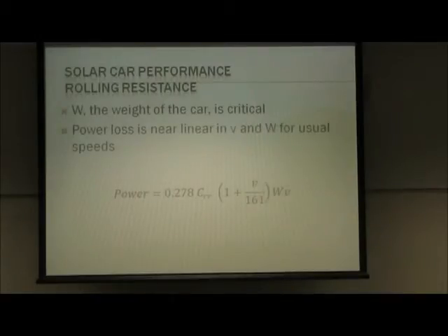And up until 40 miles an hour, that's where aerodynamics and rolling resistance were approximately equal, at least for the last car. So half of your power at 40 miles an hour, plus or minus, is weight of the car.